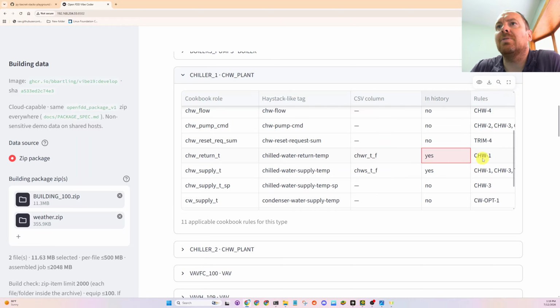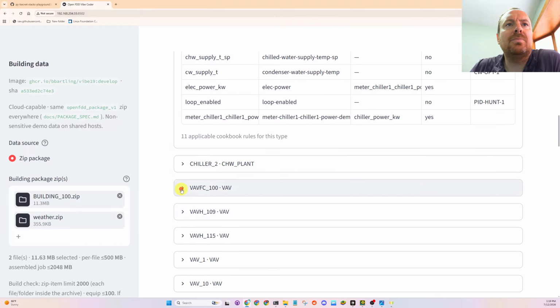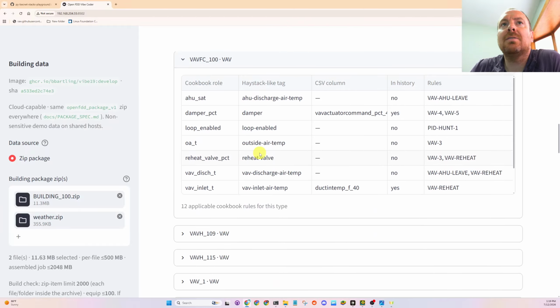Like we might need to build a way to see exactly, check out a VAV box. I can see the AI is getting confused on PID hunting. So we should be mapping that to every VAV damper output and every reheat valve.